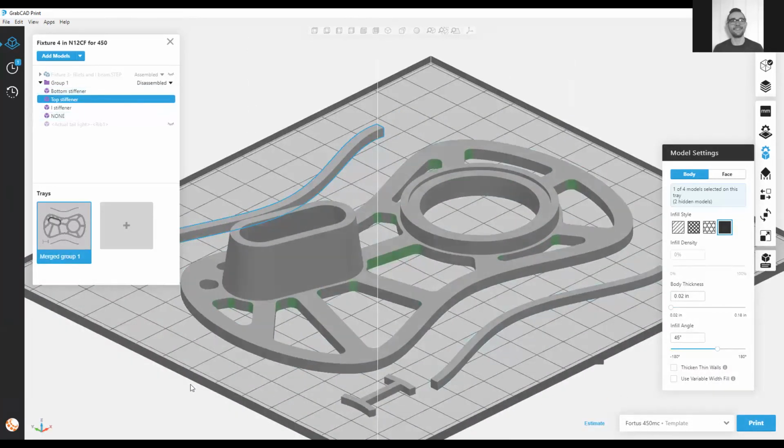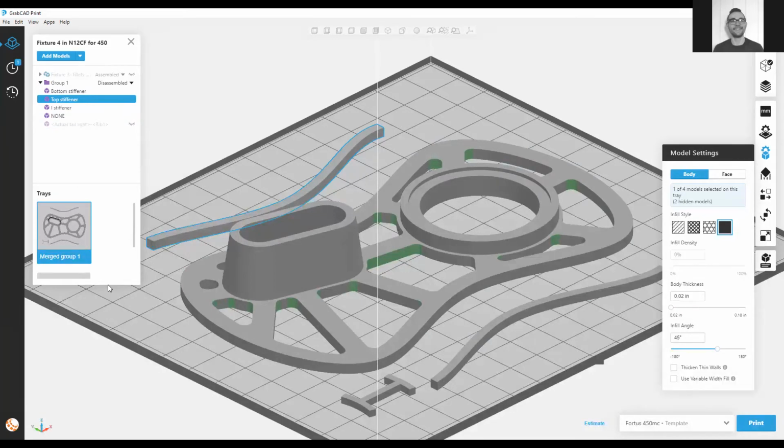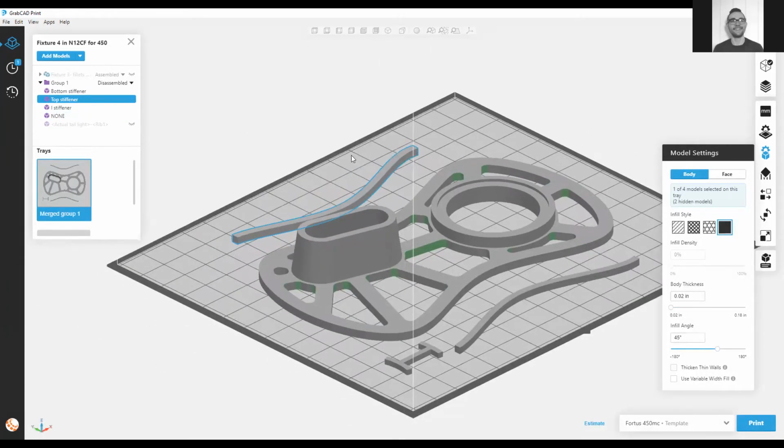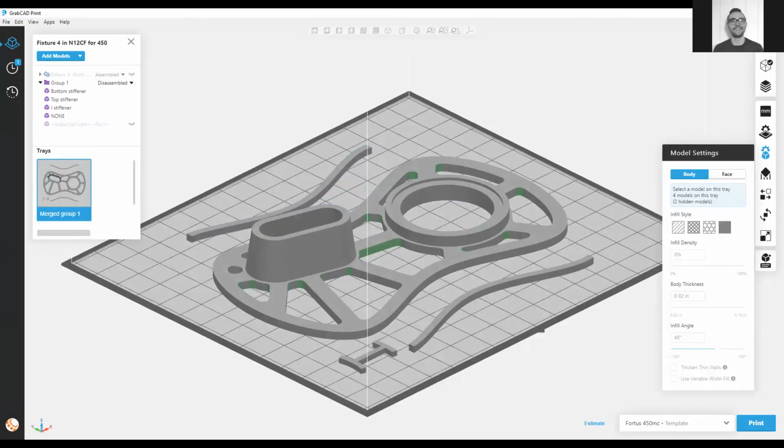Okay. So in the most recent update of GrabCAD Print, they've also moved all of the advanced FDM settings within the general print prep. Previously, it would be a separate module that you'd hop in to prepare everything and send over to GrabCAD Print. Now it's all embedded in the same workflow, so you can work on parts with advanced FDM and parts with regular processing all on the same tray, which makes things much easier and more efficient.